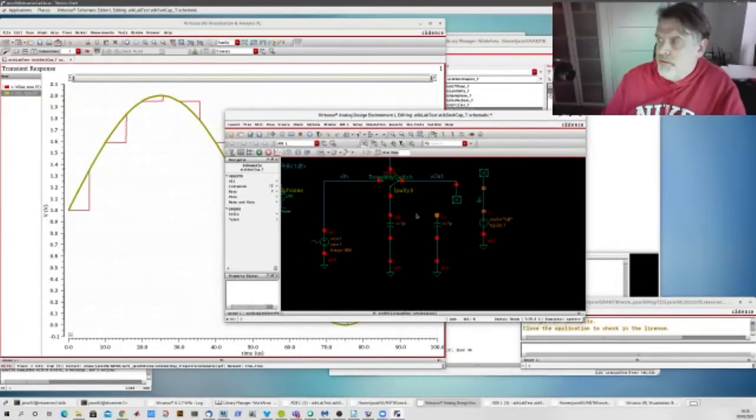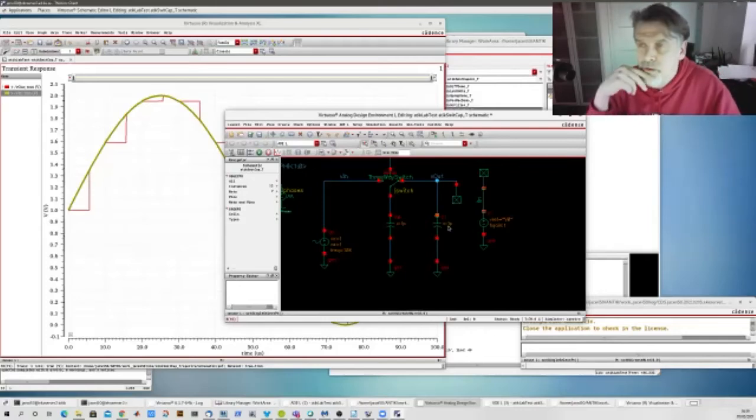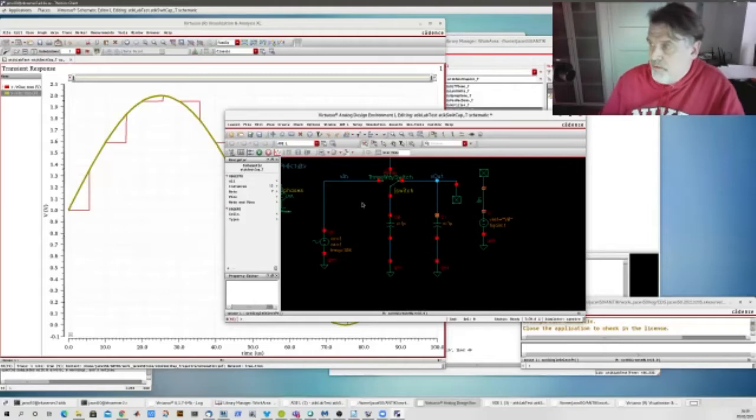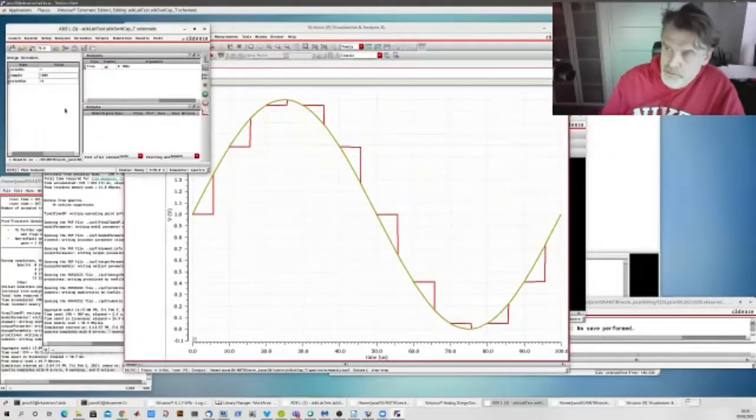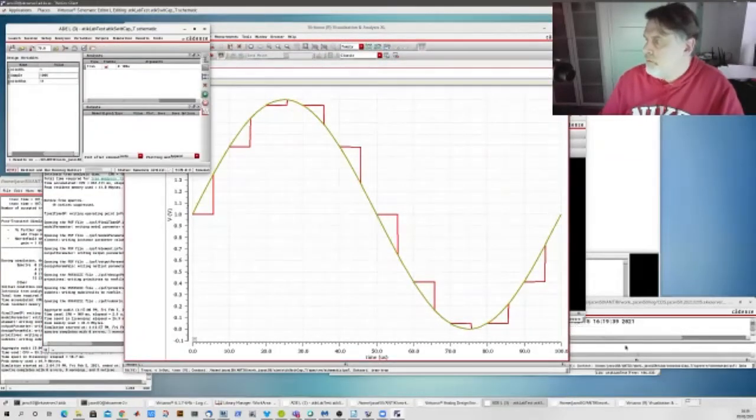And now we could also look at what happens if I connect my capacitance to the output. So now we have the case that we just investigated, a switched capacitor acting like a resistor, and then an additional load capacitance at the output. So I would assume some sort of low frequency behavior here, or filtering at least. So let's save and run this simulation and take a look at the curve. Did I get into, there we are, simulate.